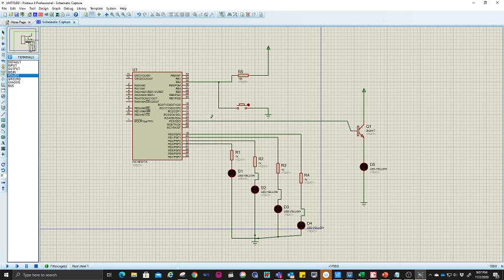So you have to give a signal out from RC0 to this one. You have to give to this one, right? Okay, you have to do this, which means that you have to give the value 5 volt from this pin to this pin. So you have to put RC5 as output. So this is RC5.